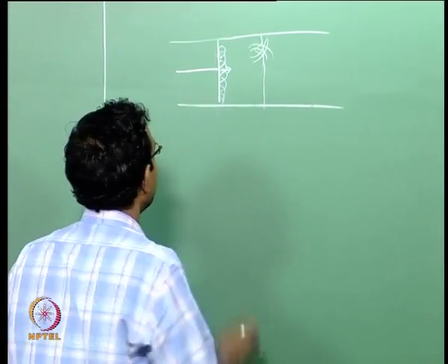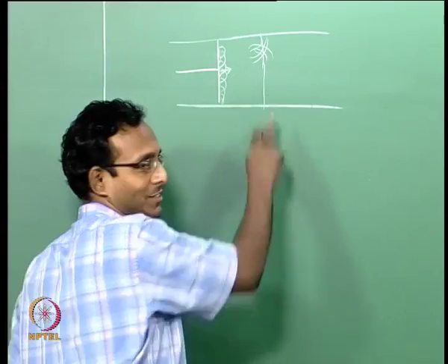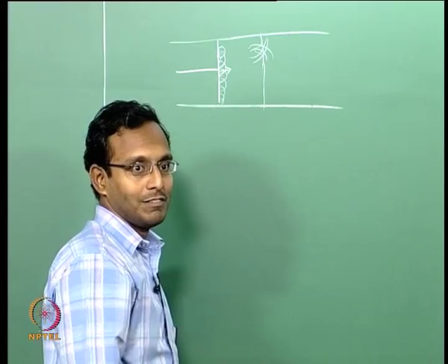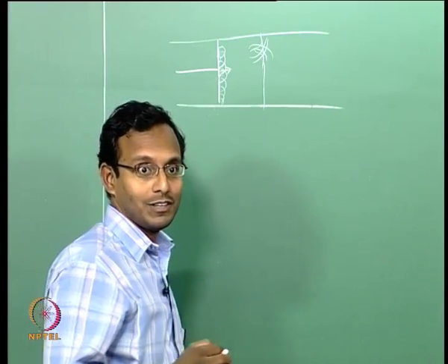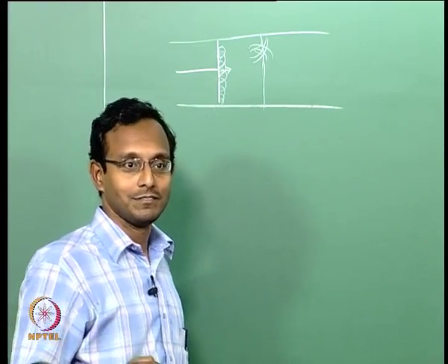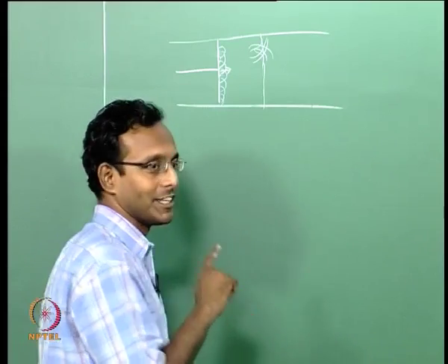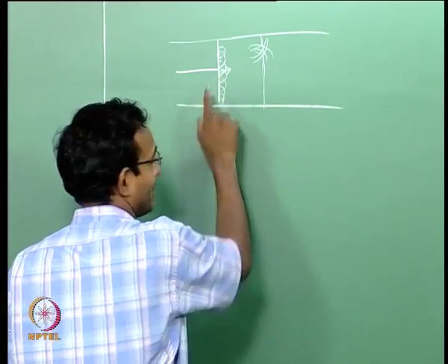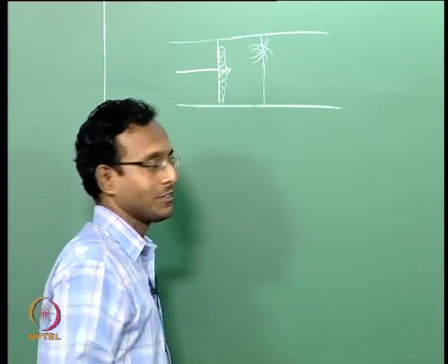If this is the case, when it moves a little bit, there is one compression wave created. After that, the fluid is traveling at the same velocity as the piston. If the piston is not accelerating anymore, then there is no more compression wave created, because the wall is not moving with respect to that fluid element. Okay. They both have the same velocity, in which case there are no more compression waves created.